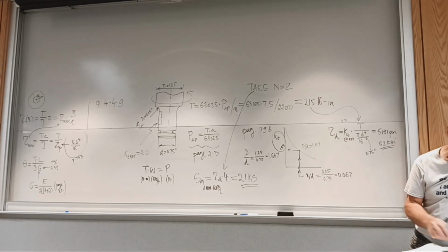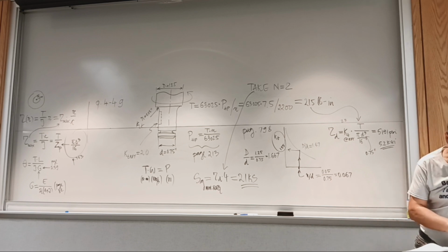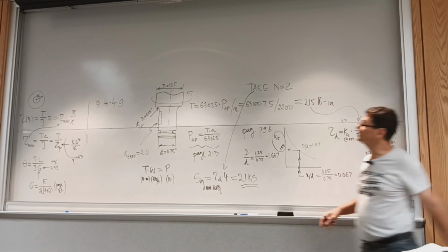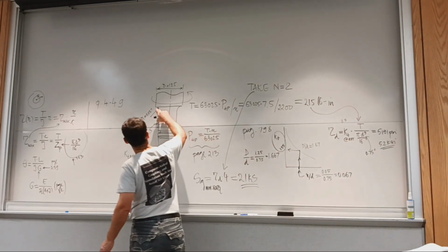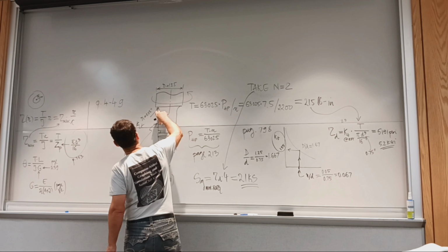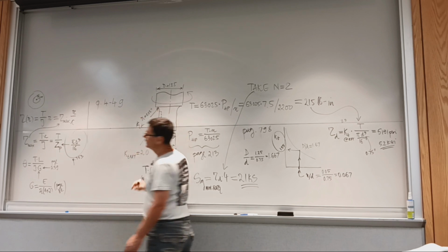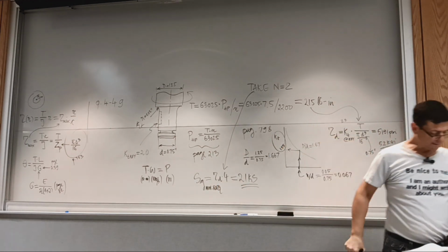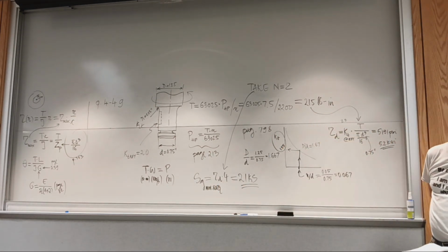And well, there's machining required, so that may go against being the cheapest possible. And we might have to harden it because there are additional stresses here, as the key induced bearing stresses. We haven't discussed this. So let's go with medium carbon, plain carbon steel.